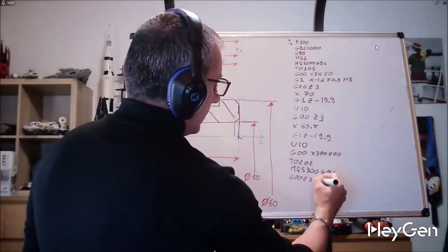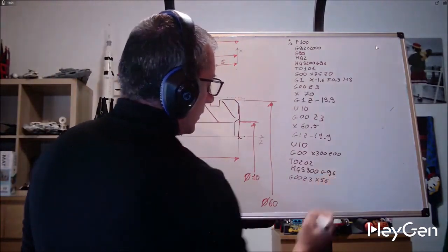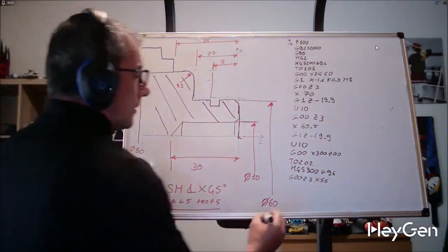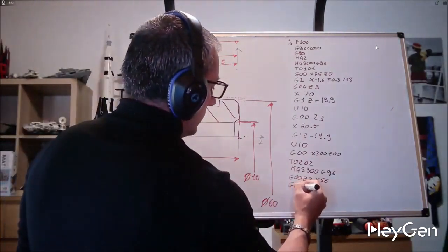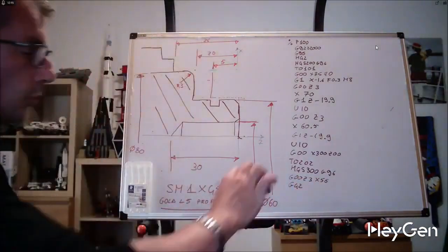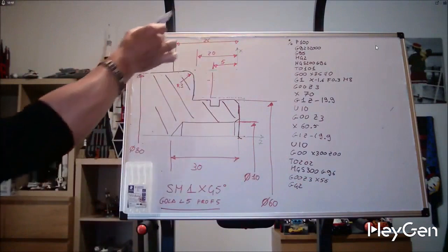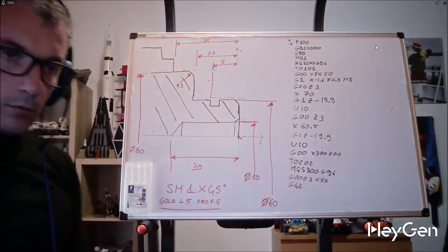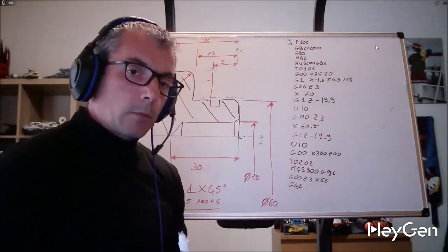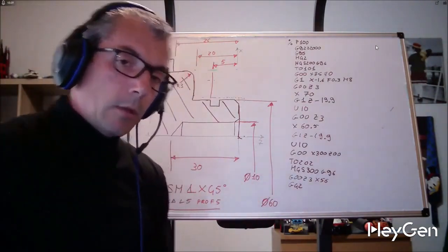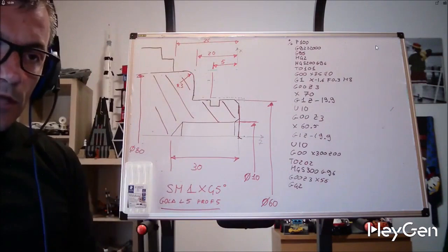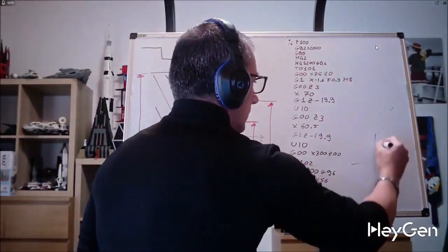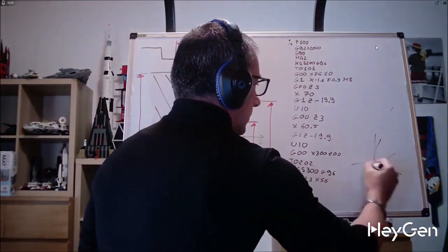At this point, what am I going to insert? I will insert my tool radius compensation, G42, because I am moving the profile clockwise. G42 will work well if in the tool table, and we will see this later when we do the first program, simulator, we will have inserted the correct tool radius and a small drawing. I would say the correct orientation of the tool.